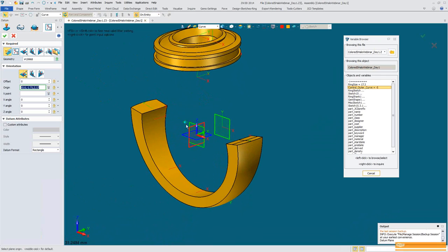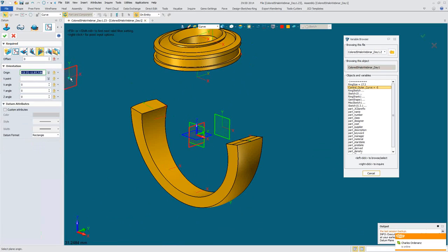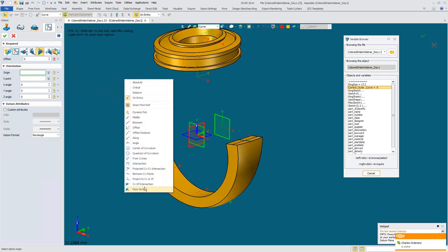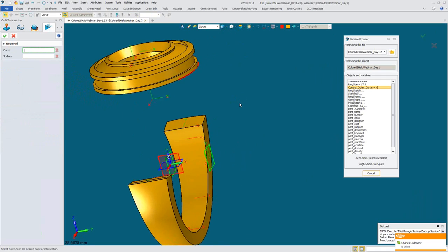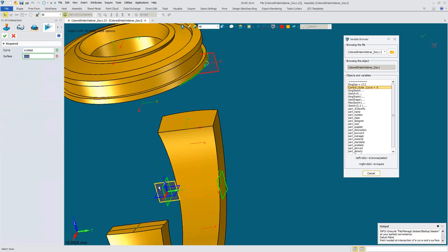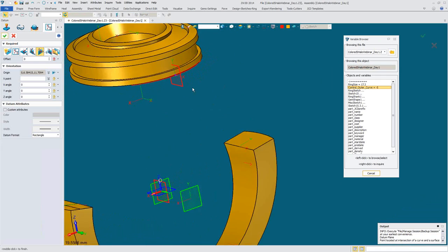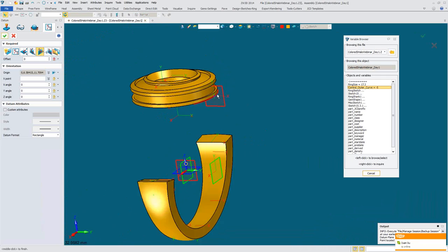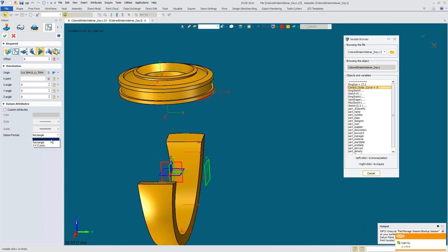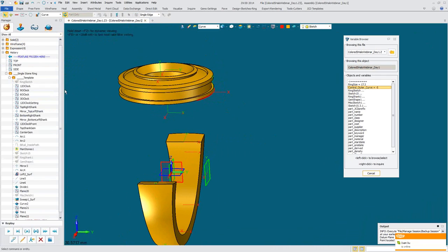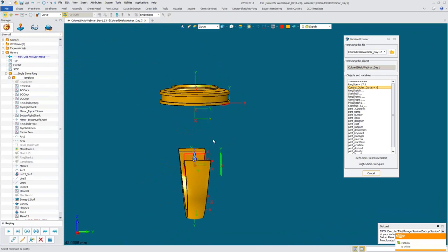or even for that matter, pick this side view, okay? Pick the YZ this time. And right-click Curve Surface Intersection. This curve and a side view, and it's nailed. We know that puppy's nailed. And OK to command. Okay?